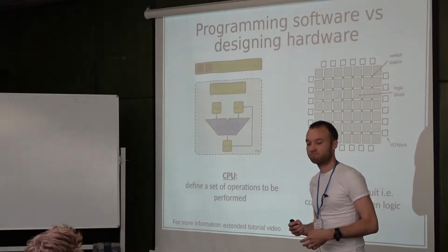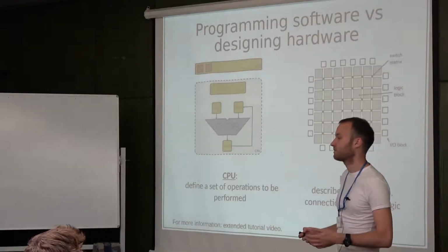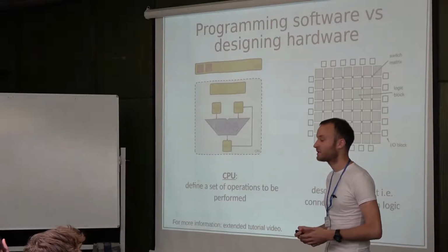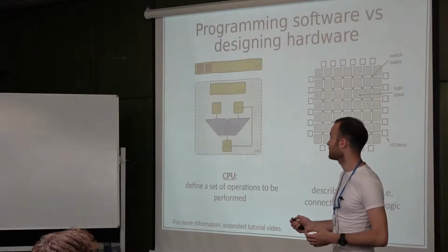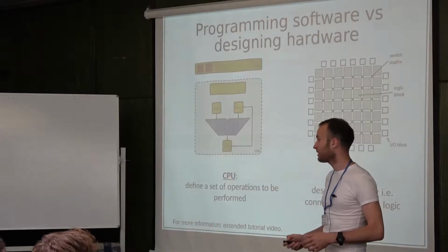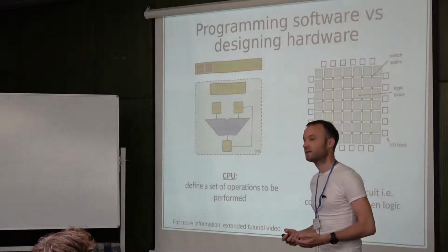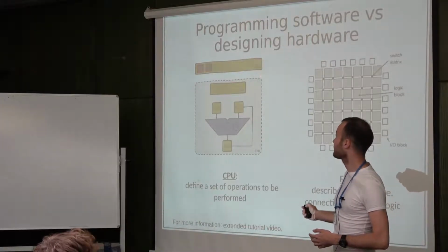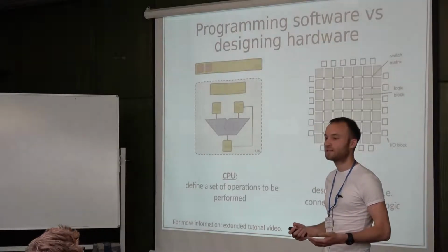This could be called DDR, DDR2, 3, DRAM. So there are different types of memories, but the common thing is that they always sit outside the chip, and this memory is energy dependent. So if you don't supply energy, all the data will be lost. But the main thing to remember is that there is always a trade-off between the capacity of that memory block and the access time. For external memory, we usually don't have any practical limitations in terms of capacity.